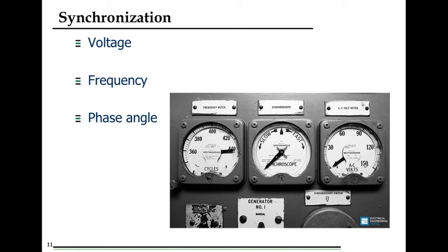So after that, when the synchroscope is rotating in the clockwise direction, there will be a mark in the synchroscope that shows it is highlighted, and at that point we can close the breaker. When the needle comes to that mark, the synchroscope will give us a permit to close.